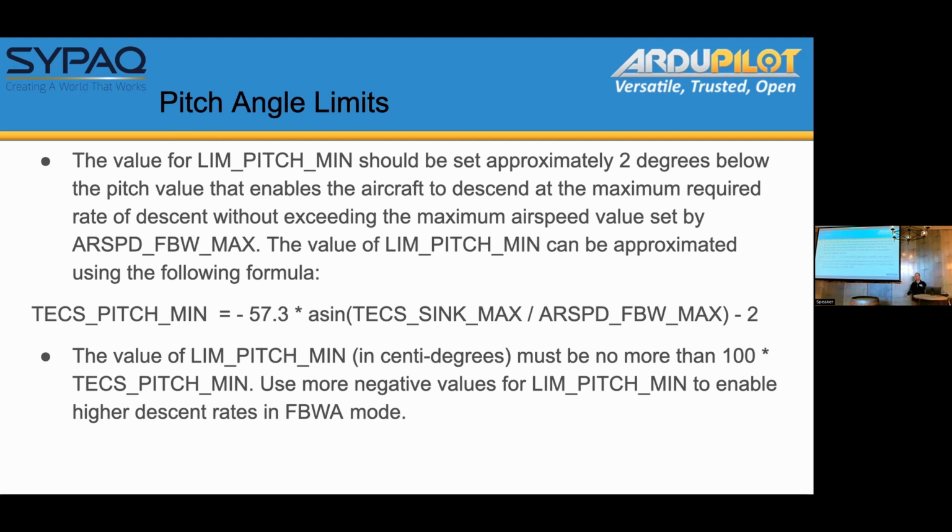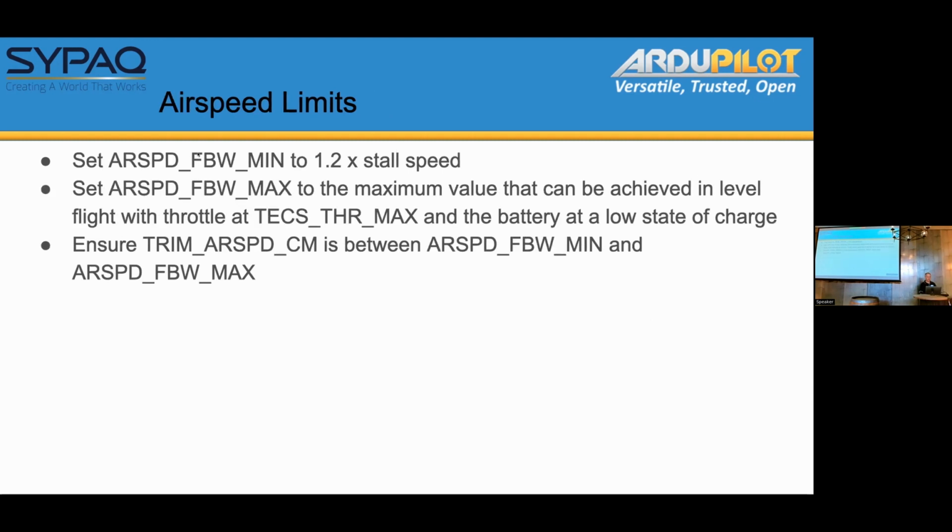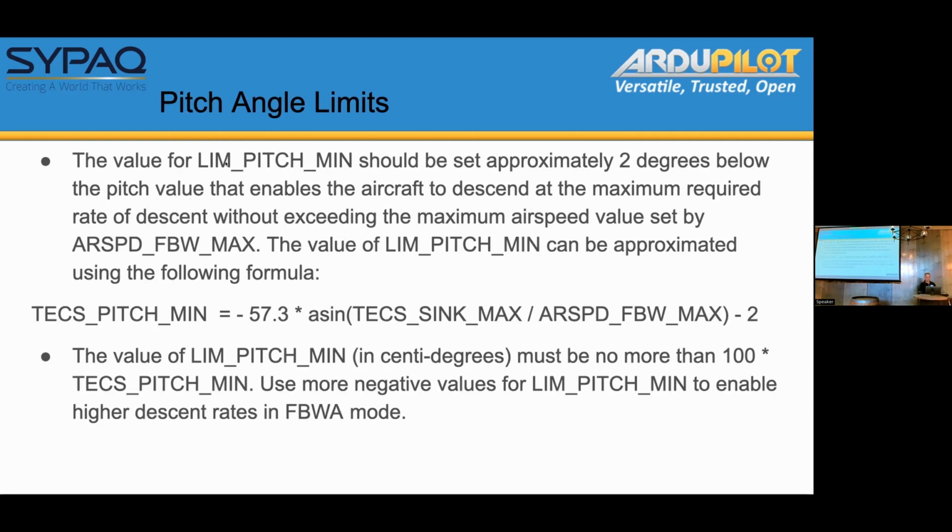So there, lim pitch min needs to be set. TECS pitch min, in the top. Oh, yes, sorry. That should have been TECS pitch min in that. Yes, you're correct, that should be TECS pitch min. I'll fix that up for the slides. The last sentence of that first paragraph. Yeah, TECS pitch min. Okay, no worries, thank you for that. Just don't want people setting it off by a factor of 100. Yes, because 70 degrees versus degrees.